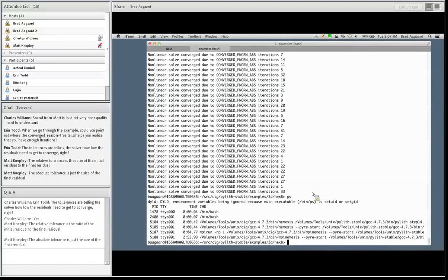If you're really interested in how much the fault slipped and how fast it slipped, and capturing that decrease in the coefficient of friction through the sliding behavior and then locking up again, then you would want to use a finer temporal resolution and smaller time steps.